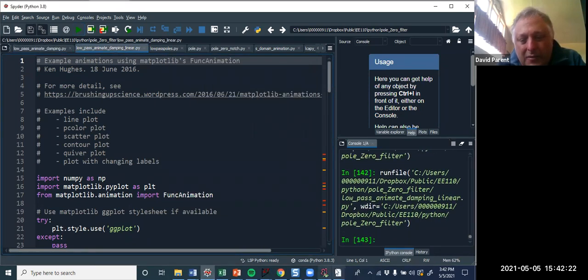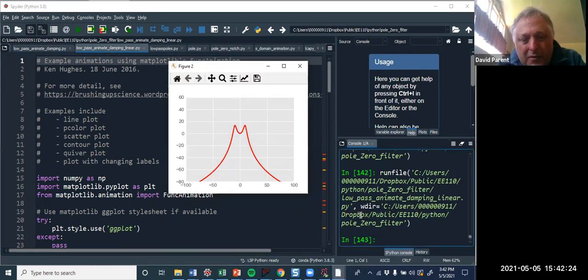What would that look like on a linear scale? Well, actually, it's still in dB, otherwise it doesn't work. But there's something that we don't talk about much, which is that in the Fourier domain, we actually have negative and positive frequency. But in the Bode plot, we only do the positive side.